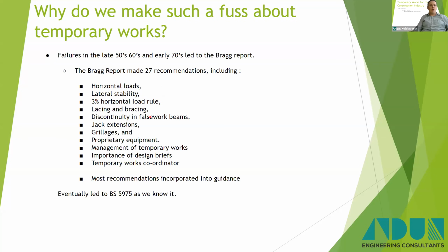Specifying lacing and bracing, making sure jack extensions are considered. The proprietary equipment has instructions. The systems in place for the management of temporary works. That's quite an important one, and that is quite a large part of BS 5975, the on-site management of temporary works. The importance of design briefs, again, that's still something that's really important today.